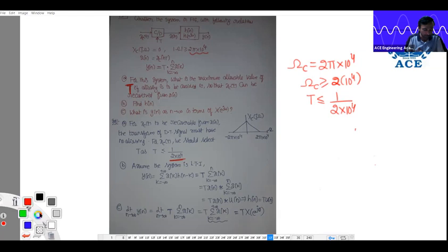Second bit asked is, find the impulse response of the system. Find h[n]. Everyone recollect our convolution formula: sigma x of k h of n minus k. See the cursor. But this expression is given in the question as what, sir? Directly the output expression is given as T into sigma x[k].